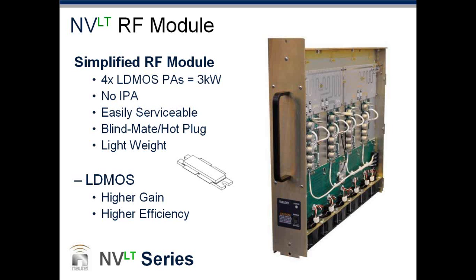topography of the silicon is such that the source, if you're familiar with FET layouts, they have a drain, a source, and a gate tab. The source is now on the bottom of the die. So that's this one here. Yeah, so it's now connected directly to the heat sink. So there's no more beryllium oxide. The thermal impedance is much lower, so you get a better thermal connection.